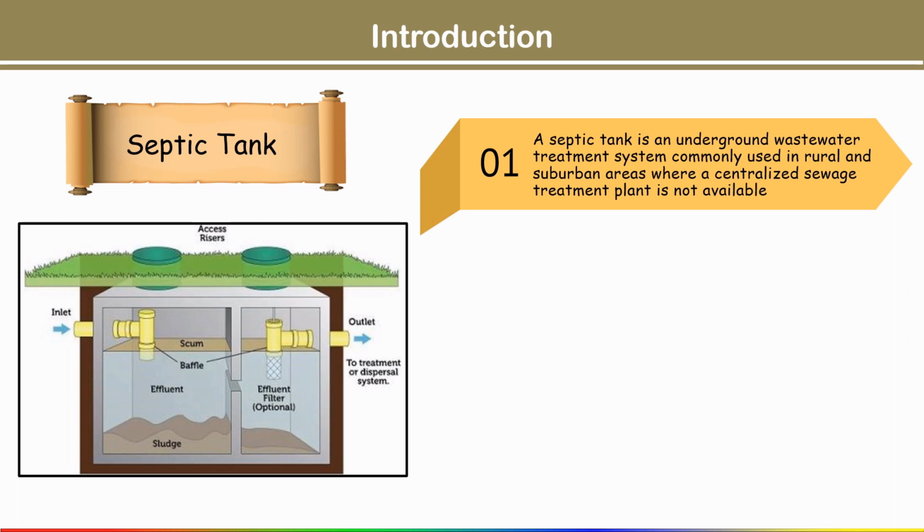A septic tank is a watertight tank designed to slow down the movement of raw sewage and wastage passing through, so that human solid waste can be separated or settled, and due to bacterial action it will get converted into sludge. This is the main function of a septic tank.